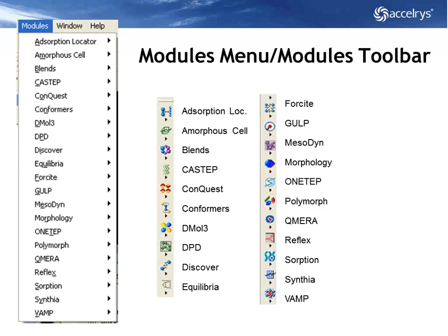Each module, and it's alphabetically listed, self-evidently, as you see on the left there, has an icon that represents what it does, basically, right? So just looking at this, if you follow my mouse, absorption sort of looks like an ethane docking to a surface. If you sort of think about this turned 90 degrees, right? A little bit of a challenge there for you. The amorphous cell is about packing polymer chains into an amorphous box, right? So that's meant to represent the box with the chain in it. Blends is supposed to be doing pairwise compatibility calculation between binary pairs using Monte Carlo theory. So blends looks like pairs.